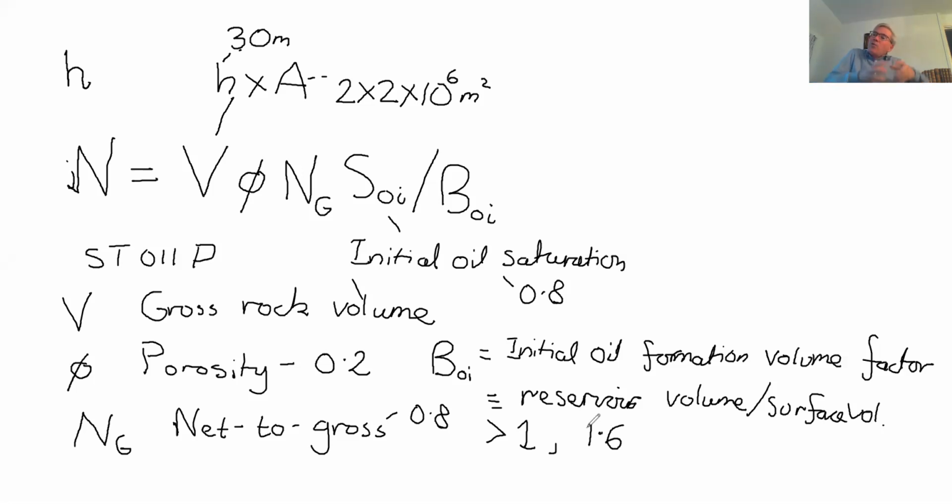When I take that oil to the surface, those components come out of the oil. What remains as the liquid phase, therefore, shrinks. And this is simply the ratio of volumes of what is liquid. The composition of the liquid, the molecules that are in the liquid, are different in the two cases. That's why you have to be careful in that definition. So in fact, what tends to happen is that things shrink.